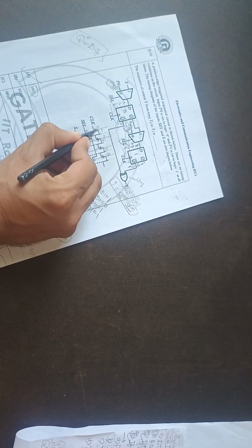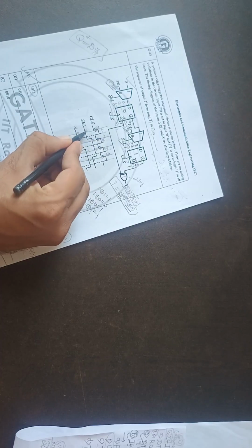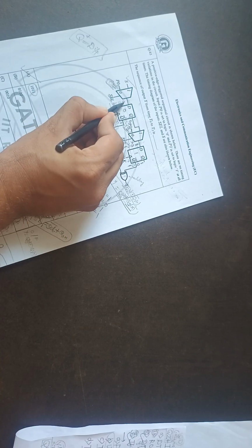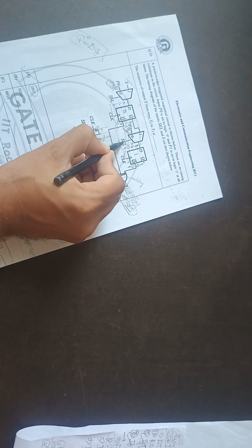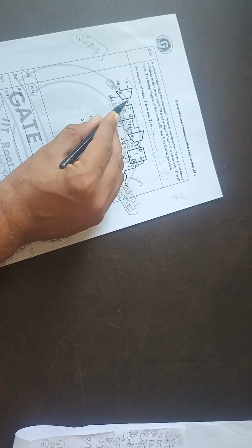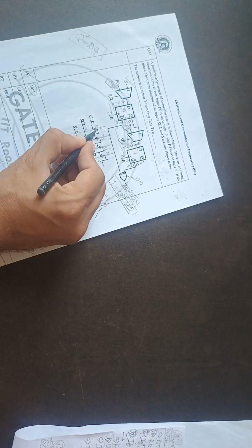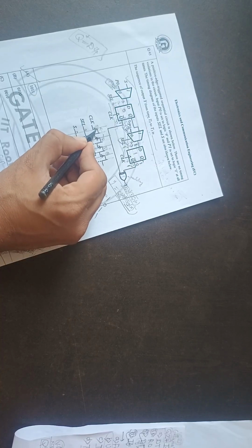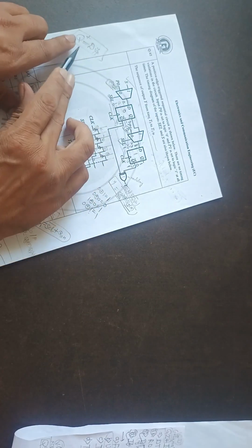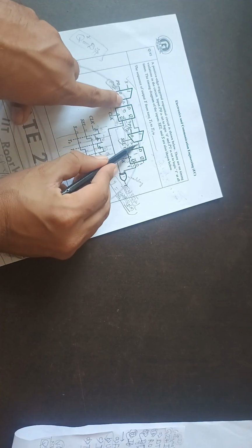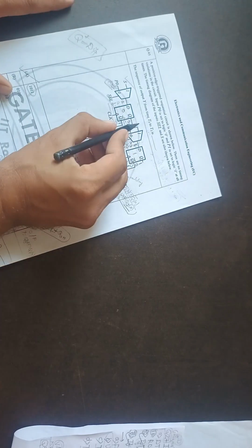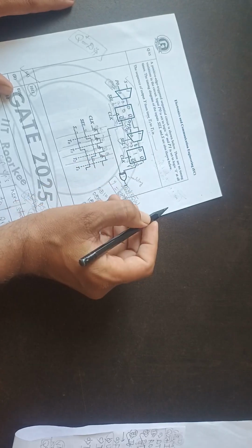Just before the first clock comes, you can see the value of select is 0 and s is 0. Select is 0 means this 0 will come here, and since select is 0, this one will come here. Initially. Now at the first clock edge, this will sample these two values, and in a D flip flop we know that the next output is the present input, so this 0 1 will pass to the output after the first clock edge as 0 1. So the output after the first clock will be 0 1.